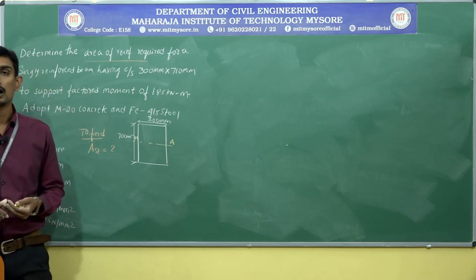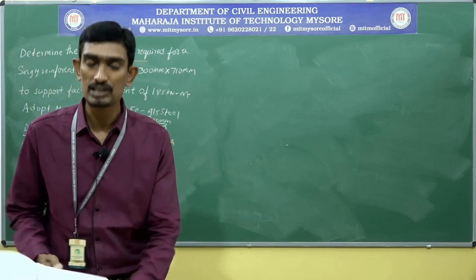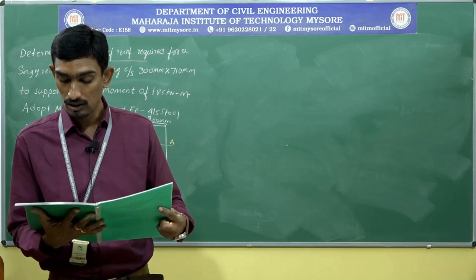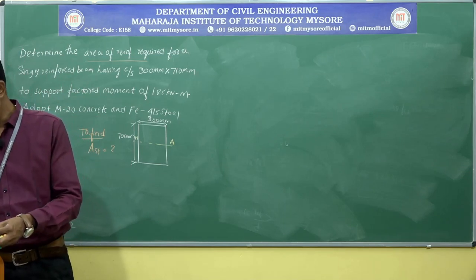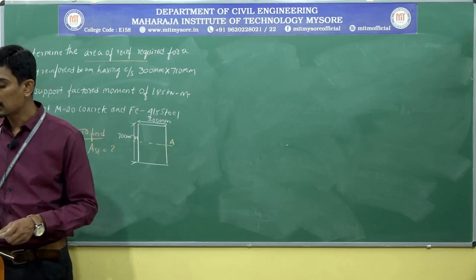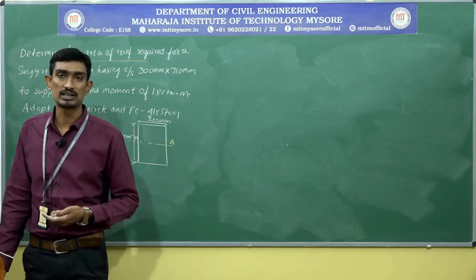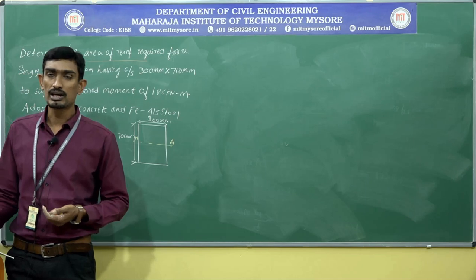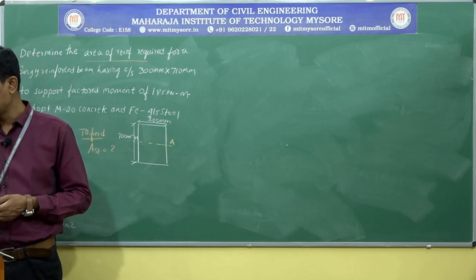So one more thing I can teach you. Page number 47, table 16. They have been given. Okay, what is the cover you need to consider in particular to calculate? Referring to there you can clearly see nominal cover to meet durability requirement, clause 26.4.2. Exposure condition. This cover may be decided, as I stated in the last class, based upon the exposure condition, whether it is mild exposure condition or moderate exposure condition. So based upon the exposure condition, we are going to decide the cover.